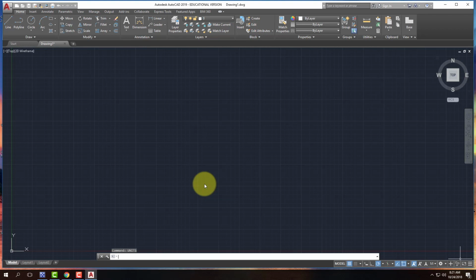There's one other thing that I forgot to put on the handout today that should have gone right next. I apologize it's not written out here. It's not on the website either, but I'm going to tell you how to do it right now. We're going to set the drawing limits. Actually, we're going to change the drawing limits from its default template. This is going to give us a little bit more space to draw. It doesn't mean that we couldn't draw a bigger object. It's just going to help our view a little bit. So go ahead and type in limits.